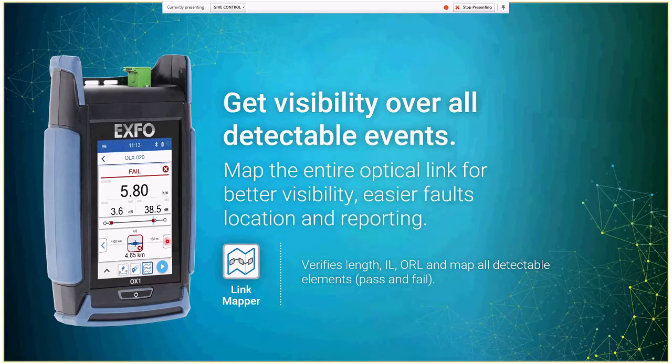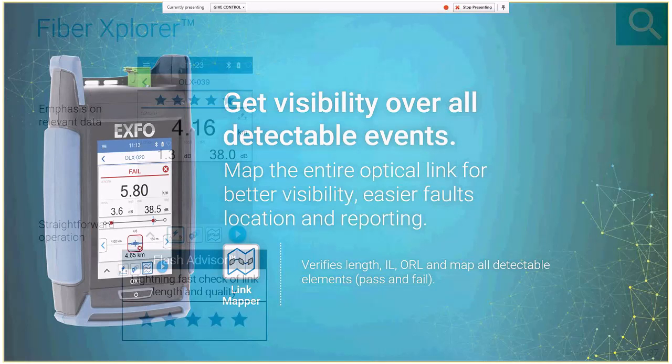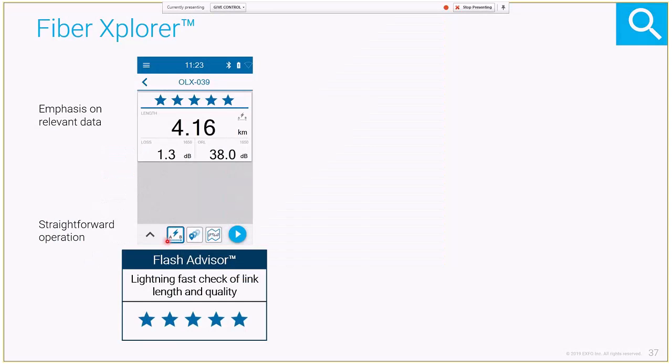It's very useful, for example, if you want to replace a patch cord or a lead inside a section of your network, and you want to find where my next connector is and how long the fiber I need to replace is. This will make your work completely quicker and make a massive difference in the way you work, without the need of having an OTDR if you don't have one, or an iOLM.